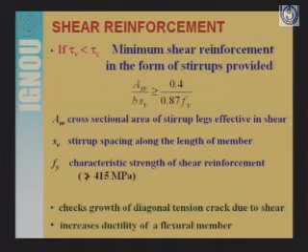Now, in case of providing these stirrups, one thing you have to keep in mind is that you should not choose a grade of steel more than Fe415 for these vertical stirrups. Generally Fe250 is used. At the most you can go up to Fe415, not beyond this grade of steel. So what is the contribution of this shear reinforcement?